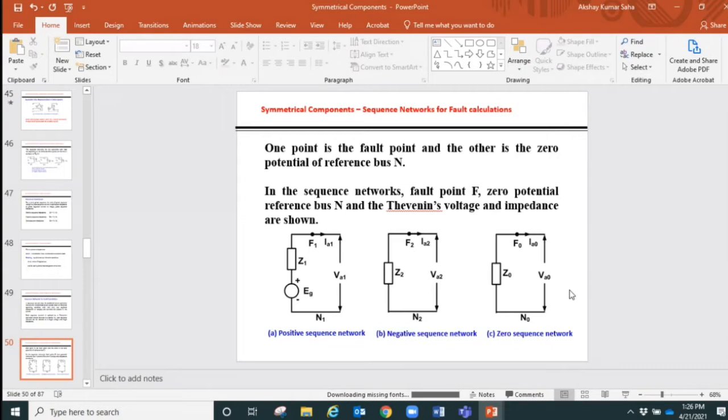But when it comes in our real life, we will have a generator, we will have a transmission line, we will have transformers, we will have loads. The load can be a motor, load can be a static load, like a combination of RLC. So when we will have those, the reactance diagrams need to be drawn accordingly so that we can look at the reactances and then analyze for the current flows and the voltages, and then calculate the volt ampere or the MVA, fault MVA, and all those stuffs.